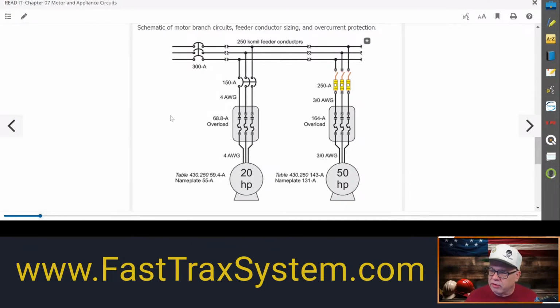So let's go on and look here. When we did our math and looked at our protection, obviously we've got them already here on the screen. So you've got this 250. If you've got the 250, that is your protection. You've already done the math. We already did the sizing for those fuses. And then you had the sum of the other, and that was 59.4. And that is 309.4 amps. You'll see how we got that.